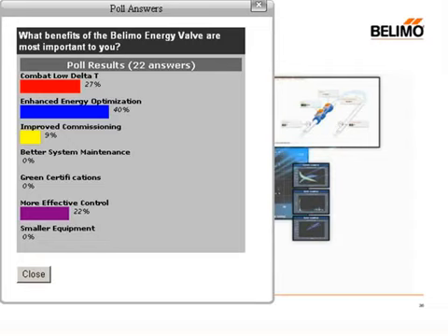I see one question here from William Sherwin. Energy Valve force delta T: if the room needs more cooling and the valve chokes the flow because the delta T is not what is desired, how does the room get more cooling? That's an excellent question. We are not recommending setting the delta T higher than what the as-built drawing, basically the design condition, is set for.